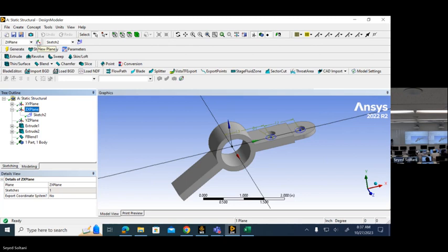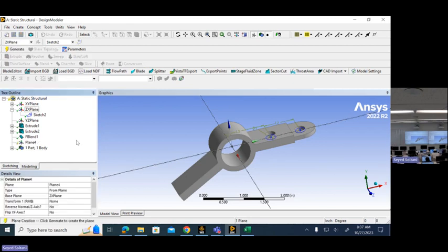Yes. See, new plane. So the new plane creates a new plane, but you're able to select the base plane. So pretty much you select this plane and then somehow transform it and position it where it needs to be. So I selected the XZ plane and I click on the new plane. So that's plane 4.